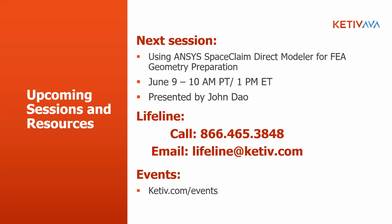I just selected the surfaces for capping and I just selected the seed face, and boom, I have my internal volume, right? So it is a more intuitive, easier to use tool with these added functionalities that will help you prep your model better. Like SpaceClaim also has a meshing feature, right? And we can talk about that in a later AVA session. So as far as preparation for analysis goes, SpaceClaim is definitely better than Design Modeler.